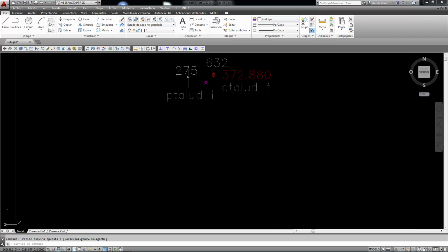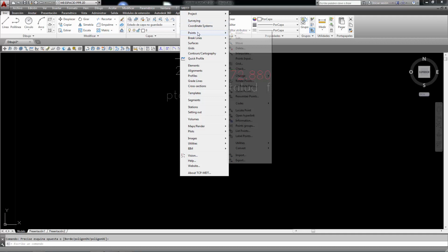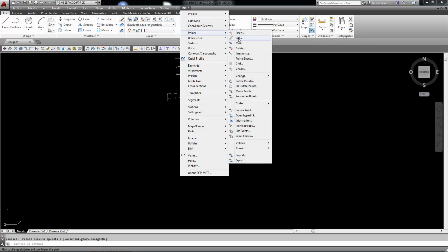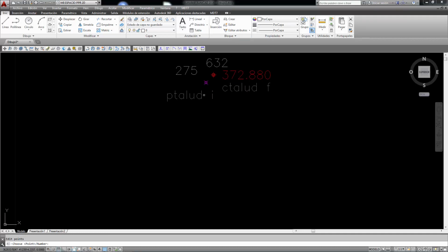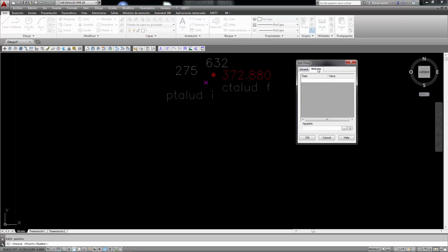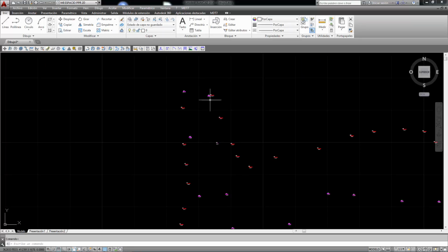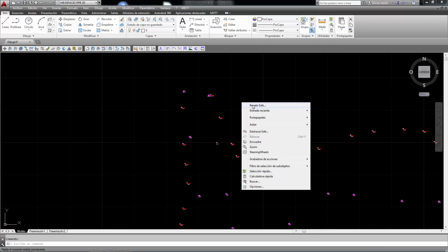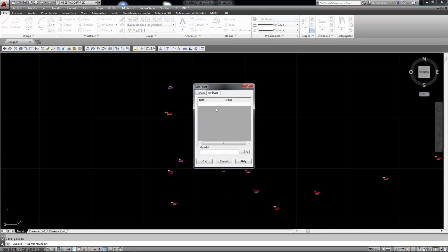For example, in order to avoid zero height points, we have the MDT Points Edit command, in which selecting each point graphically and individually enables us to correct or amend any of the X, Y, and Z features, the name and code of the point, besides an additional tab that enables us to load or add a link or attachment such as images and documents.